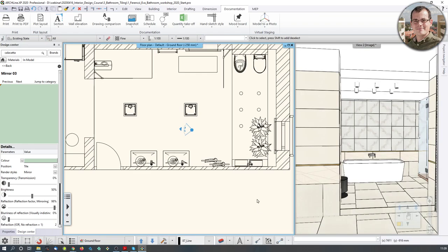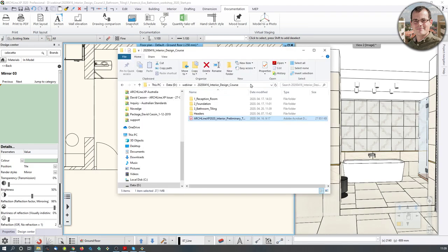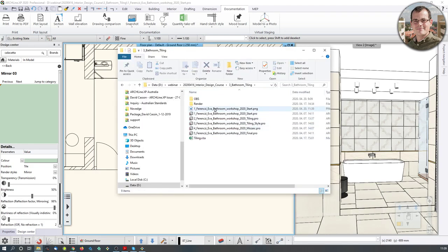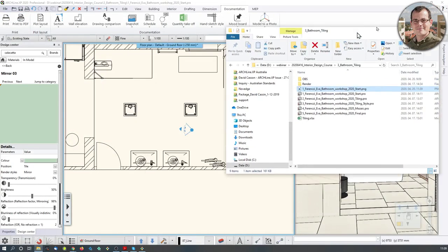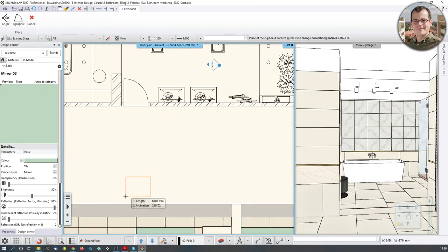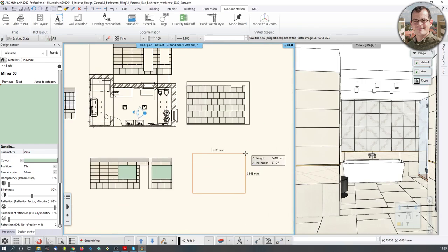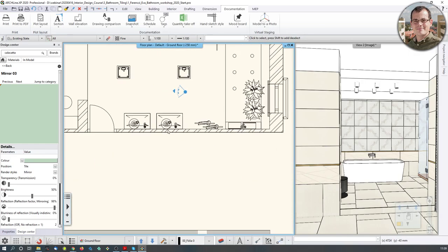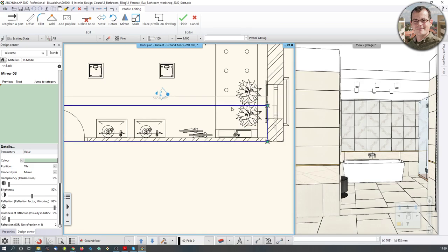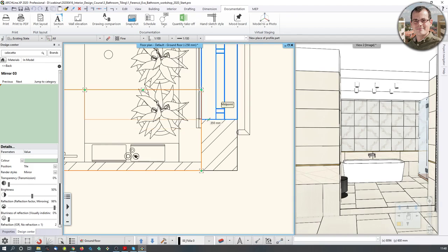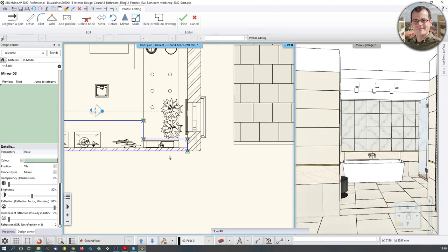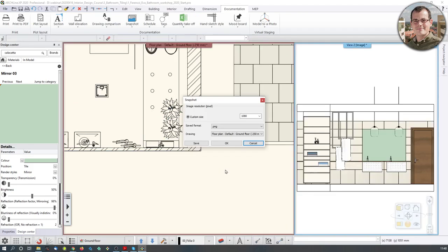And again, if you want to now get it into the design, then what you do is go to the image that you have created and just drag and drop it in. This is not going to be to scale, so the better way to do it is to actually create a wall elevation image, viewing direction. Again, I have no problems with these plans, I just don't want to show them on the floor plan right now. So I'm in the wall elevation now, so let me just hit OK.